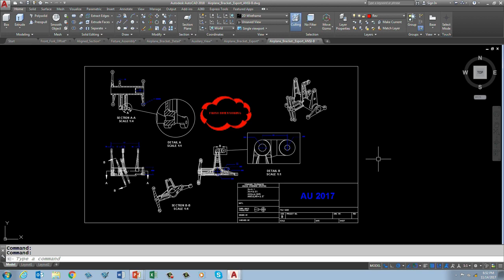And now in Inventor, you could go in and select that one line and turn its visibility off. So I've been pushing Autodesk for years. You've got to put that feature in AutoCAD. The only way you can really get it out is to do what we just did. Go ahead and export a layout, bring the layout back into AutoCAD, and then delete that feature because it's a model space feature right now. So that's a little gotcha that we have in AutoCAD.